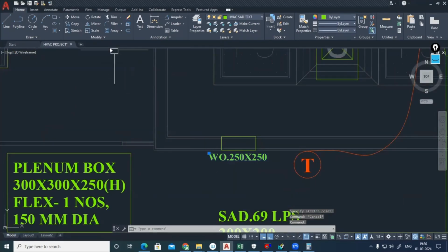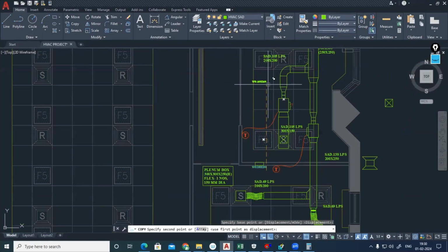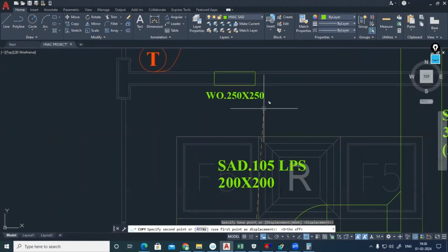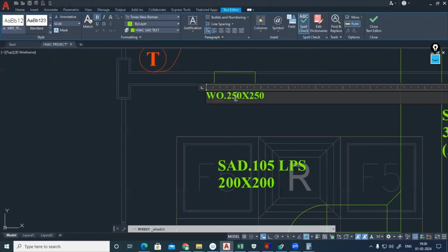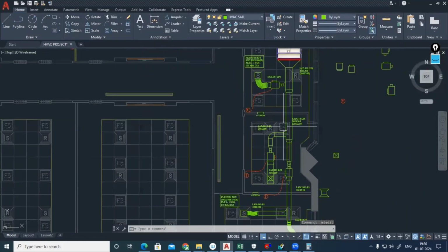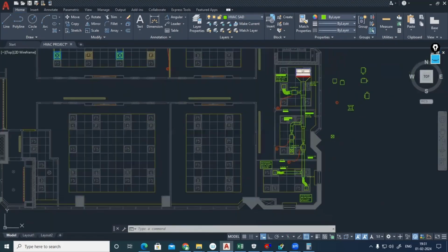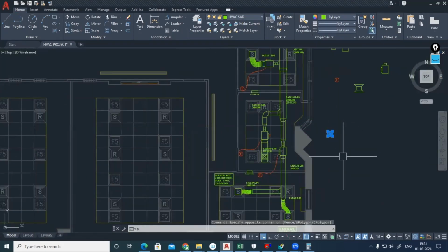So there is wall opening will come above the false ceiling. That is 300, 300. Now the return is also fine, right? Even if you are proposing transfer air duct, that is good. But leave it. Why are we additionally increasing the cost? Now transfer air duct is fine. Okay, now just let me make the schedule.